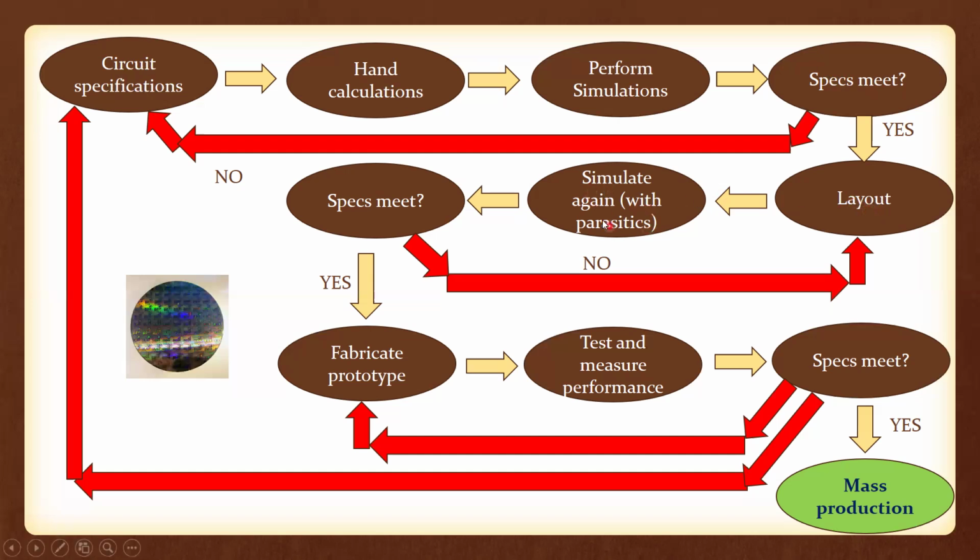And then you simulate again with the parasitics, come back to this question, and finally you say that okay, now I can meet the specification. Then you are sending the prototype for fabrication, either in your lab of the university or your company, or a foundry which offers the service to fabricate your prototype, etc.